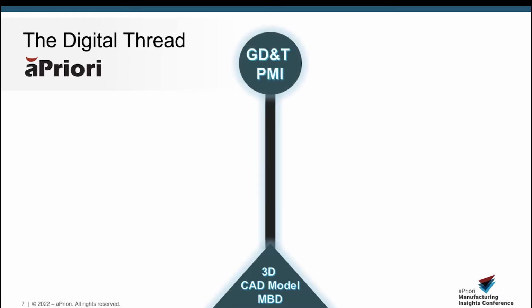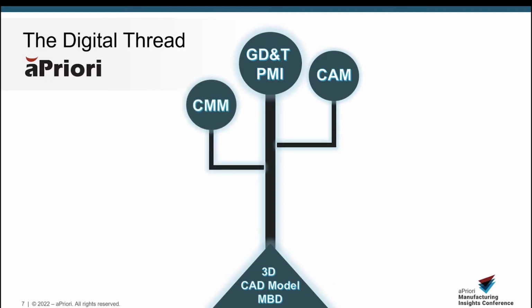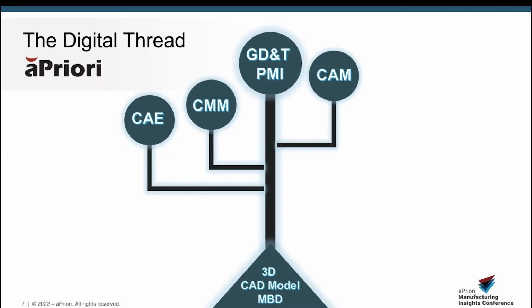By now, we have heard of the digital twin or the digital thread. But what does that mean, or what does that look like? Because we are moving towards digital workflows, it opens up a new realm of possibility and capability in leveraging machine-readable data. So it all starts with the 3D CAD model. And since we're applying model-based definition and really adding those attributes of GD&T and PMI data, it allows us to branch off digitally into other workflows. Other workflows such as CAM software. So this is probably the most common and most familiar. With CAM software, we can read the CAD models directly, understand the tolerances, and understand everything it takes to machine or manufacture this component. We've also heard of CMMs. This allows us to enable digitally where critical areas of the models are for inspection and testing purposes. Other tools like computer-aided engineering functions such as CFD analysis and FEA all leverage the 3D CAD model.